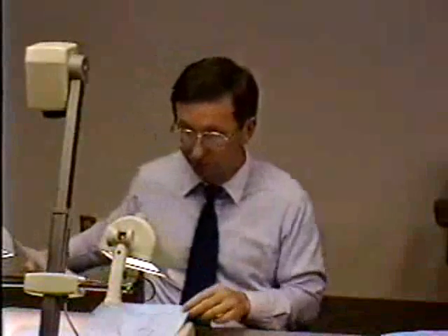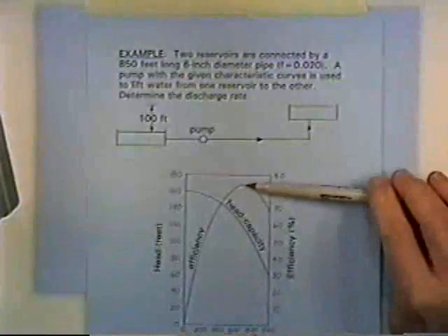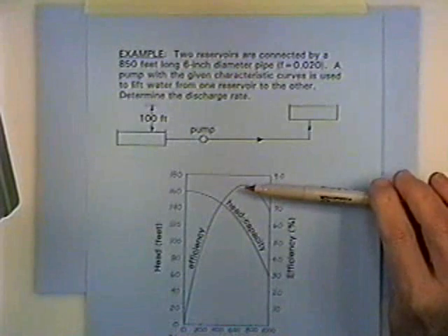Now, if you're doing this in reverse and picking a pump to meet a given set of constraints, do you like to operate this for the efficiency and the head capacity cross there? Is that the overall system optimization? Often on these curves you're looking for optimum points. Yeah, it really isn't, though. The optimum point is right here. Right here, you've got an efficiency of 82%. That's the highest efficiency you can get with this pump.